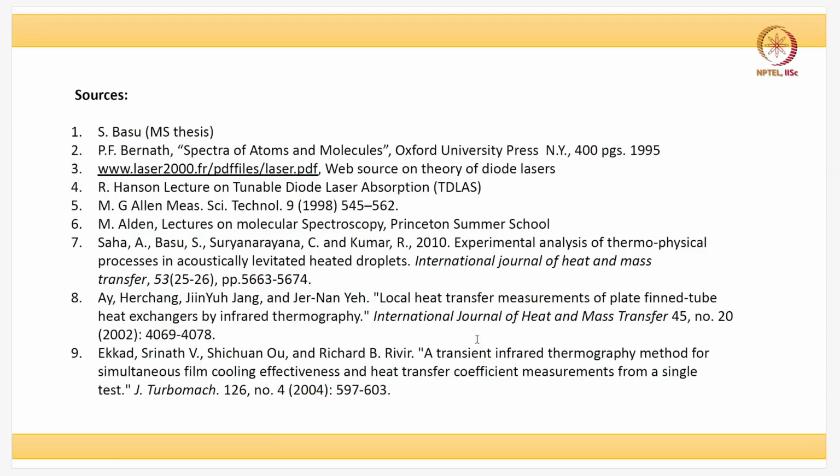IR thermography, obviously, if you have a very rapidly varying temperature, cannot measure that at a high FPS. It has reasonable resolution, but not very high resolution, so you cannot resolve at the same level as your normal CMOS 4K cameras, for example. So there are certain limitations, but still it's a field measurement, and because it's a field measurement, it has a lot of utility in the community.